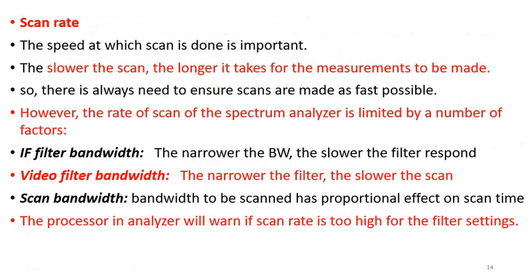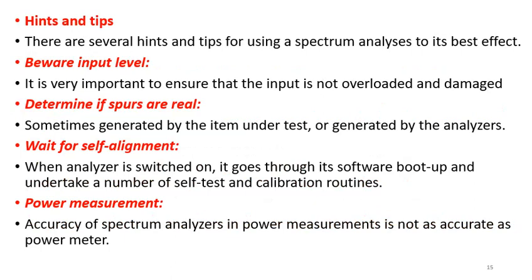Okay, as we have maybe said, the analyzers are always operated using integrated circuits or processors. So whenever you try to use a processor with a very high rate of scanning, there is another problem of generating heat. If you look at all these factors, it means you have to do what we call trade-off optimization. Try to increase the scan rate to a safe value, because if you go beyond that, one of the problems is heating, and heat is always one of the reasons why electronic systems are destroyed.